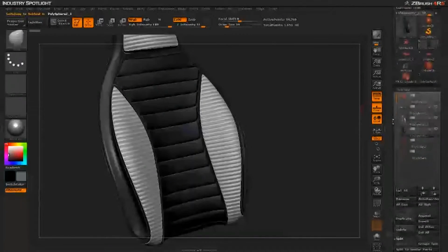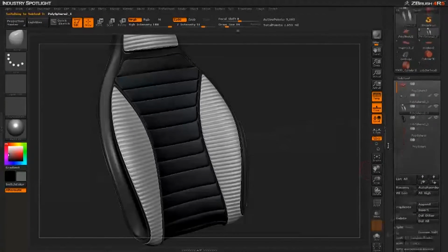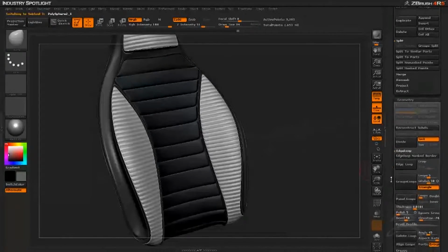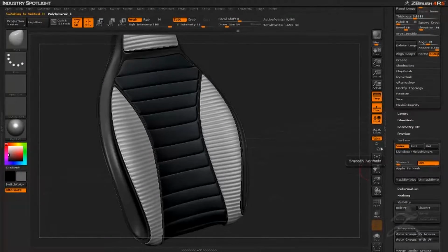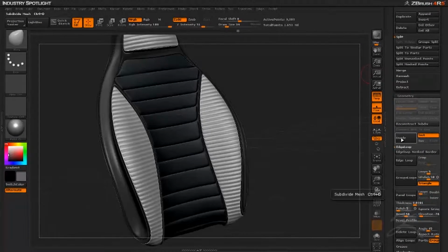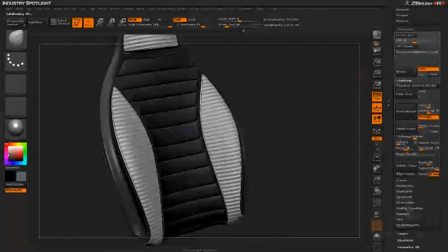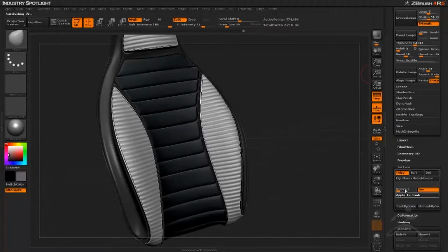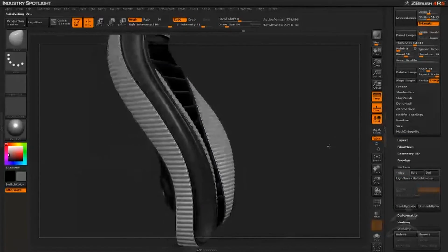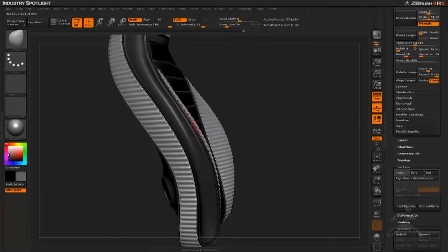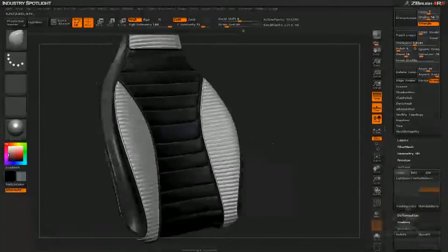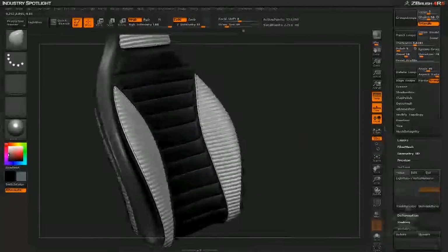And if I come up here, it's going to be a little easier to play with. So coming back down to our noise, we could apply to mesh, but right now I need to change the geometry, so divide. And 500,000 should do the trick here. Apply to mesh, it's probably going to go, well, it's actually not too bad. It made it a little bit large. Notice how it's poking out of the corners. We need to reapply that,